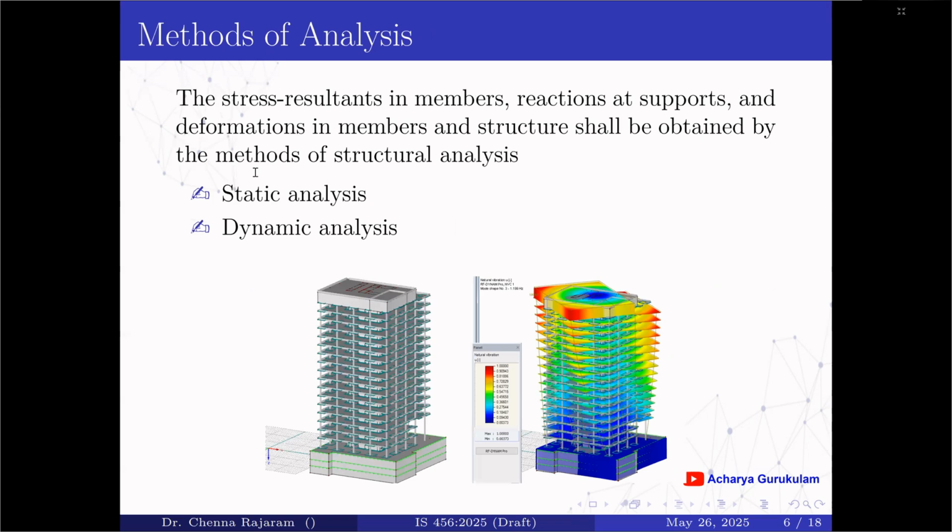Method of analysis. The stress resultants in the members, reactions at supports, and deformations in members and structure shall be obtained by the methods of structural analysis specified unless otherwise stated. First one, static analysis. So what is static analysis? Static analysis shall be deemed to be sufficient when it is acceptable to represent all loads by equivalent static loads and when inertia forces are not significant.